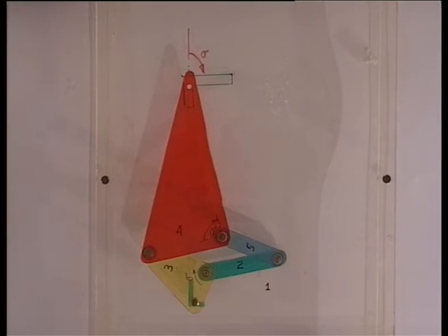As a second example of this kinematic analysis through the link vectors, let us look at the model of this mechanism, which is a copying mechanism or pantograph. What we see here is that this is a 5 link mechanism, the fixed link, and there are 4 moving links 2, 3, 4 and 5. And the dimensions of these links are such that this forms a parallelogram. This link length is equal to this link length is equal to this. And these 2 triangles are similar triangles, that is this angle is same as this angle and this angle is also same as this angle.